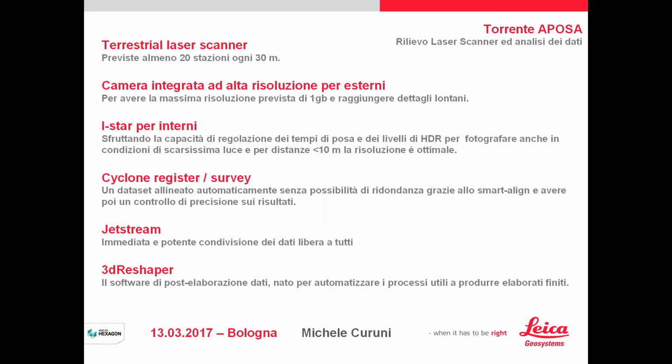And then, okay, Jetstream to have a fast share of the data, because Jetstream is a free viewer where you can see the point cloud and measure on the point cloud, so very, very fast, and it works in streaming. And then I used 3D Reshaper to create the final deliverable.